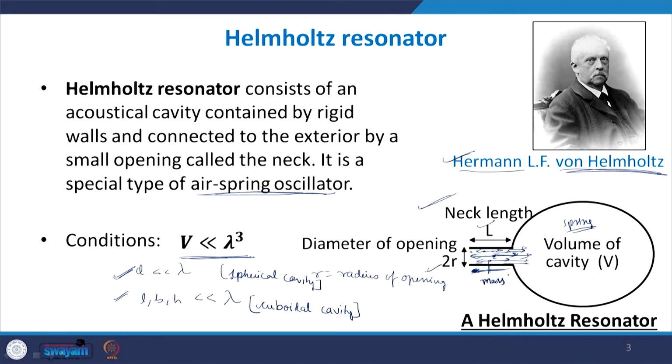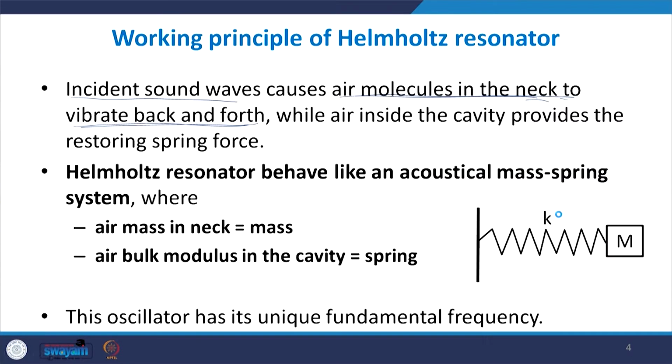The mass of the air inside the neck is being driven, oscillating back and forth, and the opposing or restoring force is provided by the resistance to compression and expansion of the air molecules inside the cavity. So, this becomes the air spring oscillator. It behaves as an oscillator and acoustically couples at its fundamental frequencies.